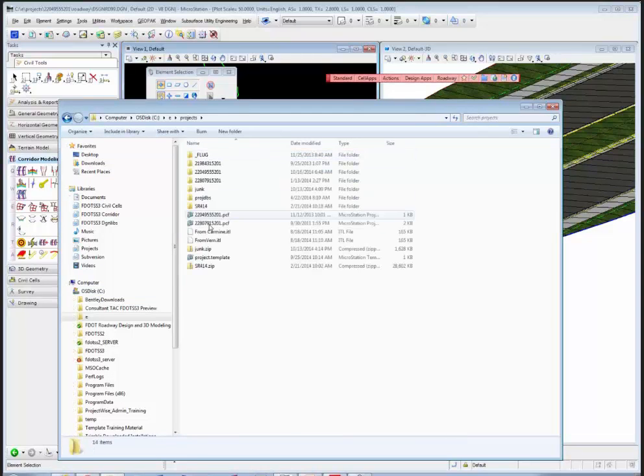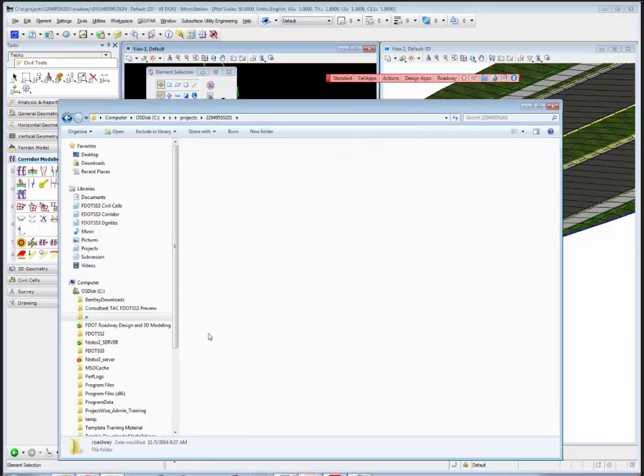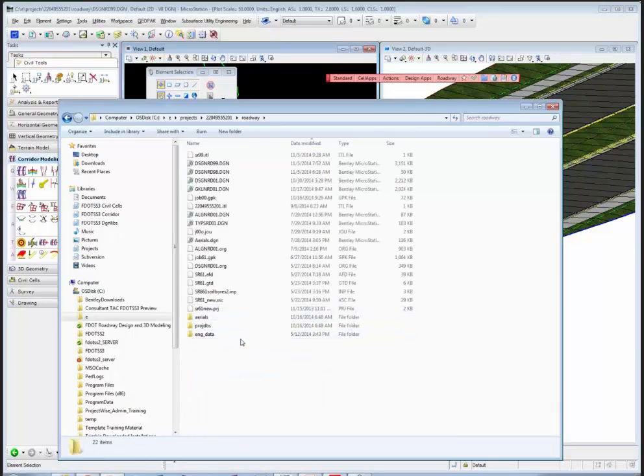Well, that means that if you have in your project, in the roadway folder, an ITL file that is named the same as your project folder, then we can default load this ITL file on startup, and every time you get into that active design file, it will look in the directory for this ITL file, and you won't have to always go back and load up and do a file open on it. It kind of works the same as a save preference.